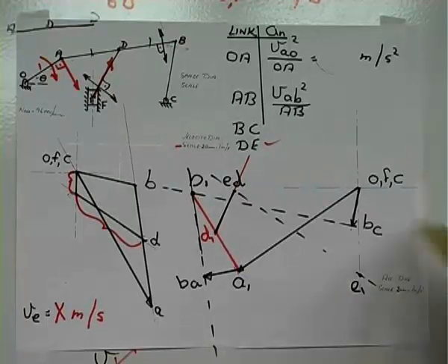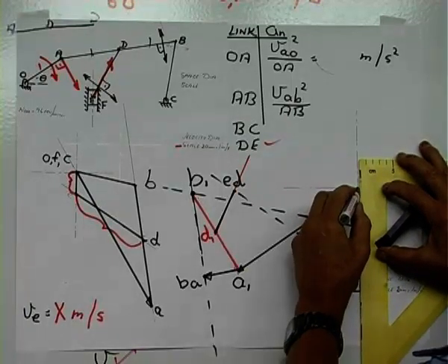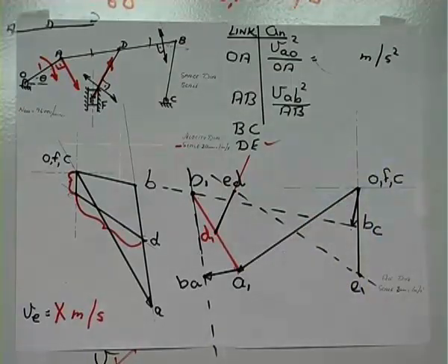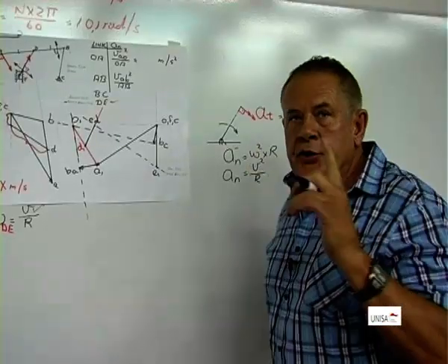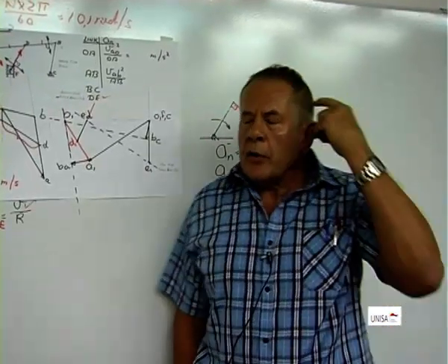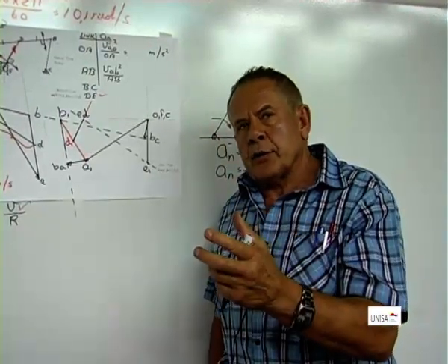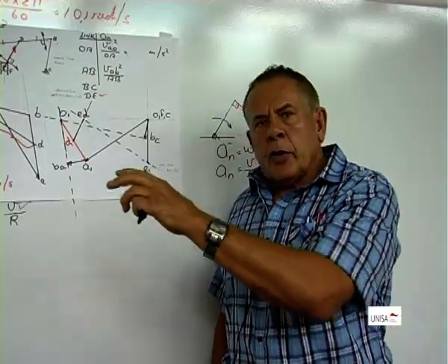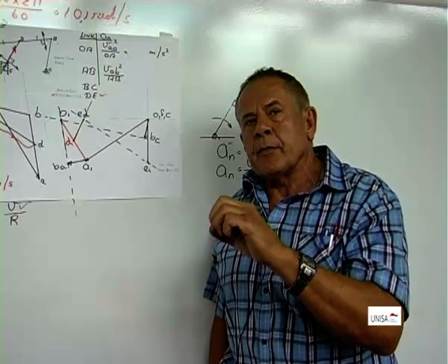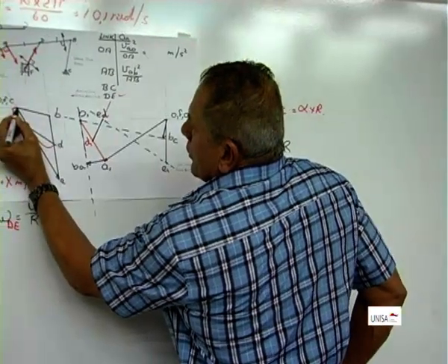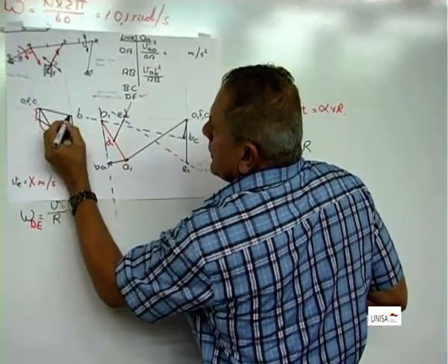Let's darken that line now. Dotted lines, and your acceleration diagram is complete. All right, the directions are also important. We only work with absolute accelerations and velocities. If we use relative velocities and accelerations, that will be only where you do have a slider mechanism, where you deal with the Coriolis component.